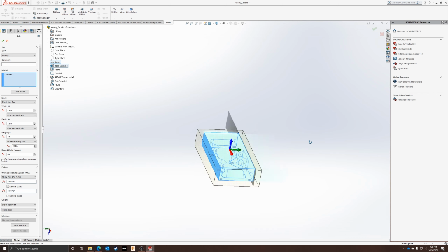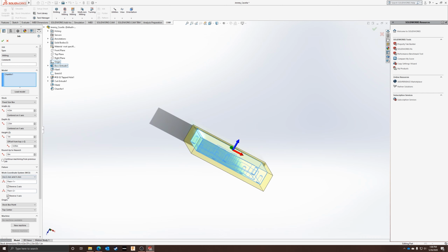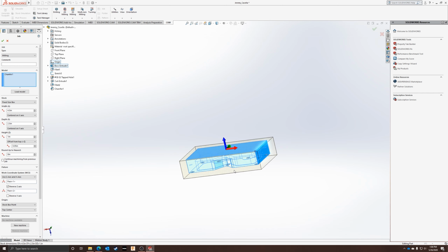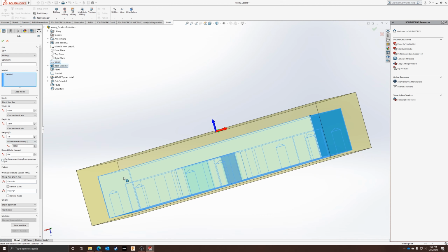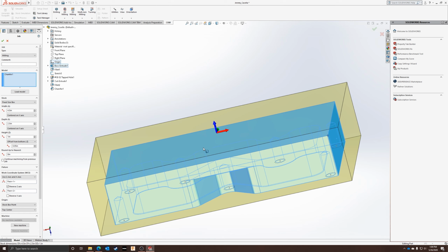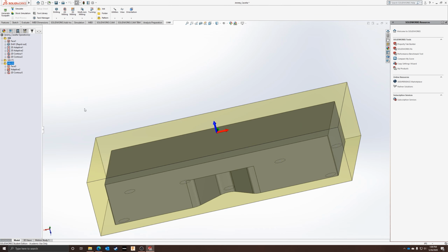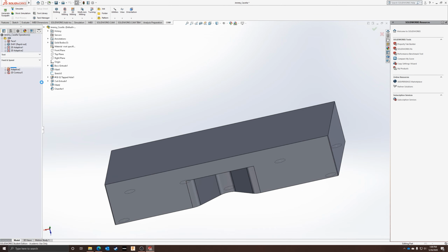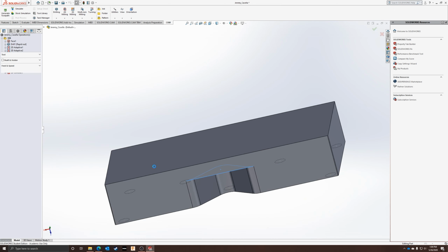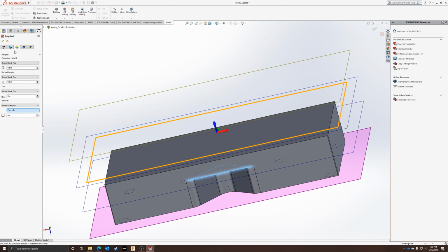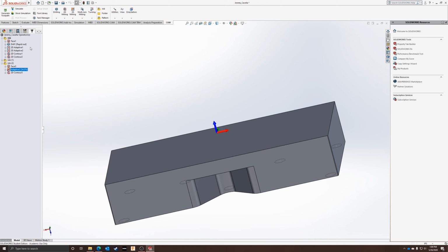Now that Z's changed, we want to look at it from the right direction. We'll reverse. It really doesn't matter. But you'll see we have a problem. It says there's 0.05 inches when this should be up there, right? We know that there's a lot more stock than that, right? So offset from bottom so it matches the other operation we just completed. And hit check. We just edit it, regenerate the toolpath, boom, adaptive. We just need to make sure we're going down to the right depth, which in this case we already are, so I just regenerate it.